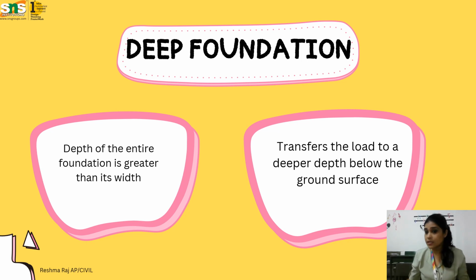Of course, the deep foundation has its own design. For the design and the construction methodology, every type of deep foundation has its own methodology. So if we are going for that construction, of course it will take more time than shallow foundation. Of course it will cost more than the shallow foundation itself, since it is going deep into the soil. This much depth we need to go with the steel and concrete, so it will take cost and time also. Another important thing is they require specialized equipment, materials and skilled labor for installation, which can increase project cost and construction time also.